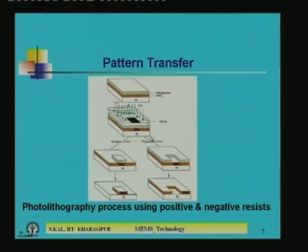On the other hand, if you use negative photoresist, under exposure to ultraviolet light, this portion to this portion to this portion will be hardened. So, here it is hardened, and only in the black region will the photoresist not be exposed to ultraviolet light. As a result, here it will remain soft, and in the developer solution this particular region of photoresist will dissolve. Okay. So, with positive resist, the same mask gives us this structure, and with negative resist, the same mask gives us this kind of structure.